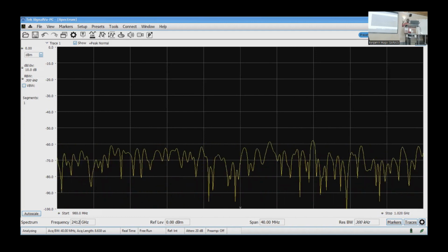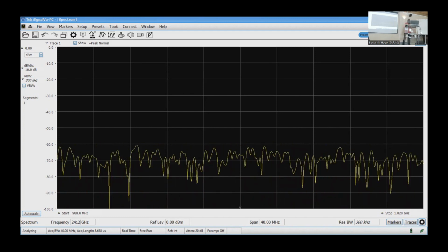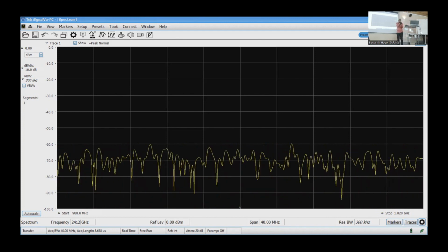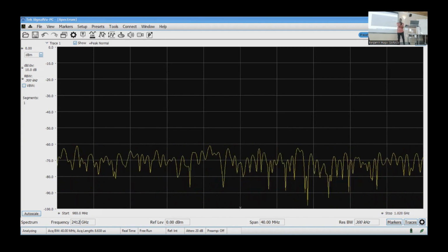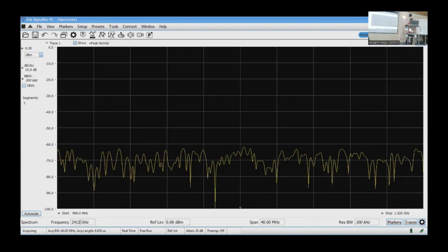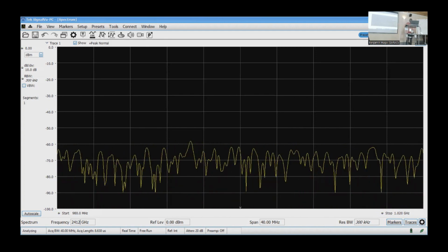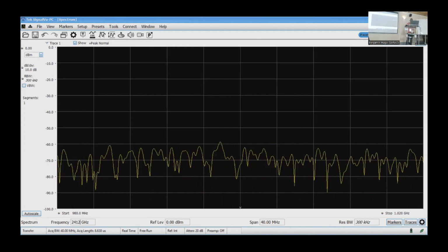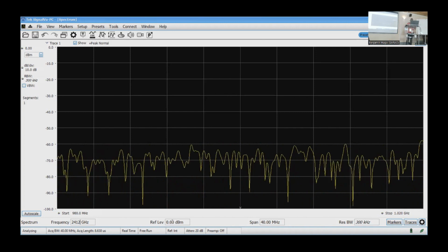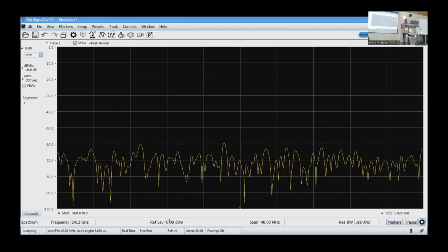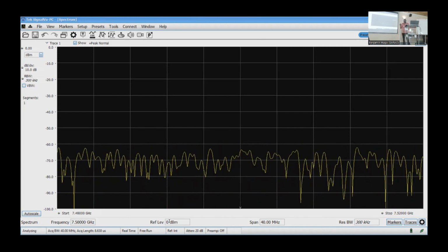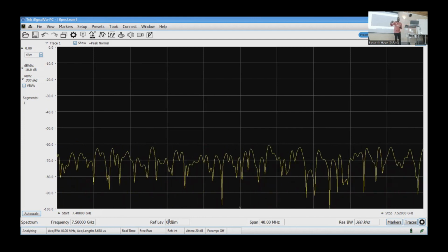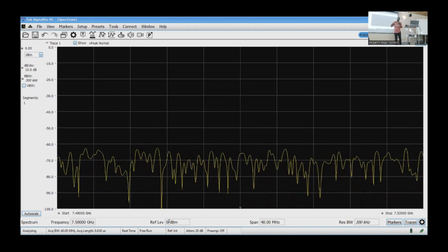Are we together? So then you must tell the spectrum analyzer the center frequency of interest. Then you can span around that center frequency to see what you capture. Remember I said you have to identify the frequency that you want to operate. Then we have the reference level. Along the signal path, you must provide some gain or attenuation.